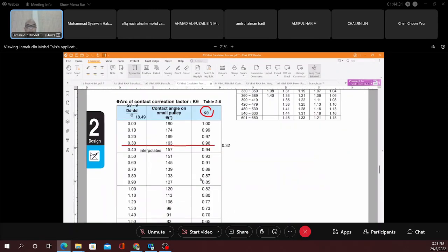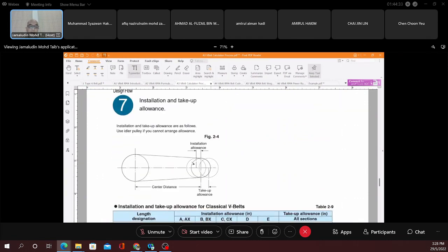However, when you try to install the pulley here, the pulley must be movable. Otherwise, it doesn't work, because the belt is of fixed length. For example, to install it, you make the center distance closer, insert the belt, and after that, you make it to the configuration.